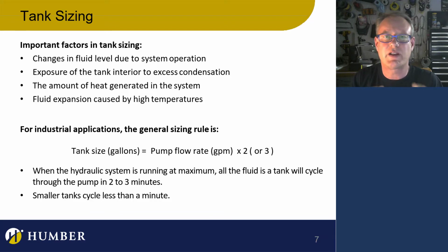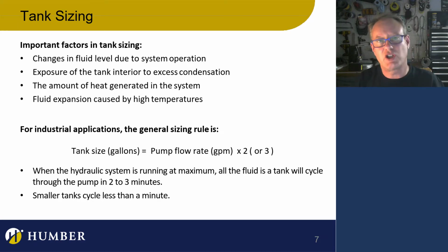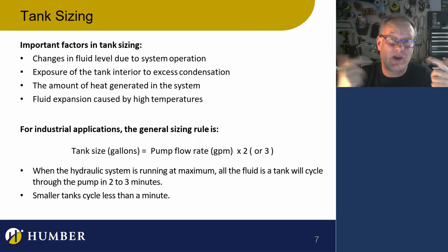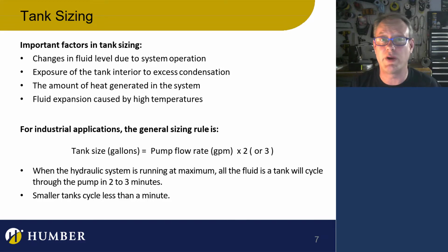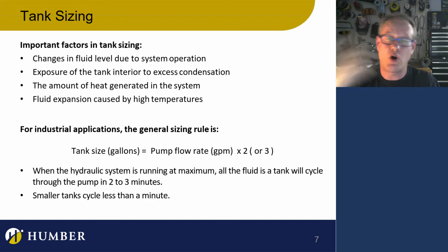Or more specifically, there's energy going into heat. There's energy going into the fluid itself. So the pressure loss is energy getting sucked out of the pressure and put into heating the actual fluid. So the fluid ends up getting hot as it comes out of the hydraulic system. It ends up getting really hot, especially with motors. Motors heat up the fluid quite a bit because they're turning all the time. The fluid's going through all the time.